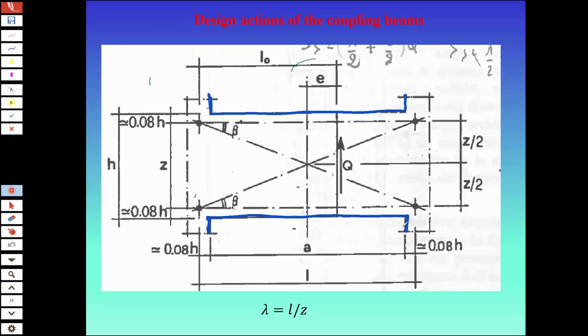Well, that E depends on where your counterflexure point is. Because the counterflexure point is, you know, in a beam where your moment is 0. So if you cut your beam there, only shear forces pass.